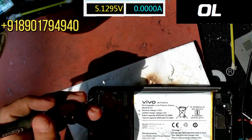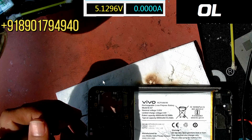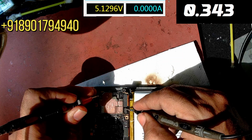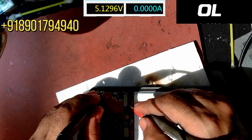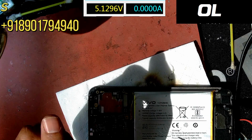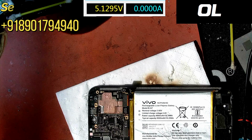Now we check in diode mode, on reverse bias. This is ground, and this one is positive: 343 diode value on reverse bias. In forward bias it's 1000 plus. It's okay according to the multimeter.